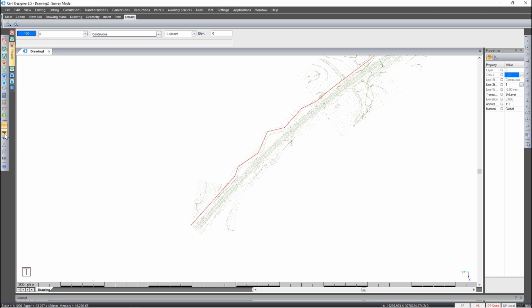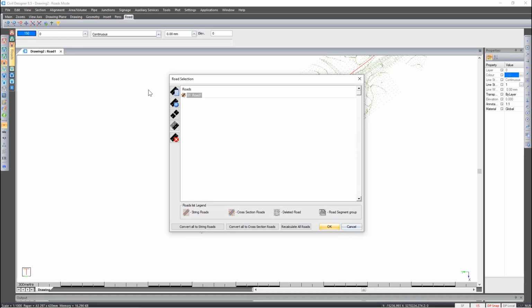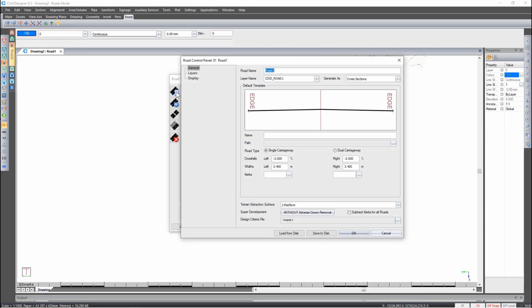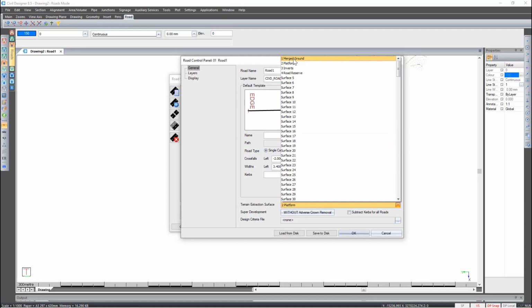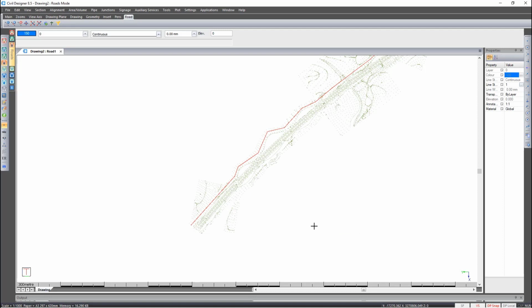And because we're using a roads function here, you go to the roads mode and then just ensure that you are in fact utilizing the correct surface. With that in place, you go to Signage, Add Road Linear Furniture. Indicate the polyline, so we've got the polyline in place. We're going to use a standard mode. In that case, this linear road furniture will be applied along the full length of this polyline. The furniture, and I'll explain this in more detail shortly, will be a fence furniture. The post distance between each other will be 20 meters.